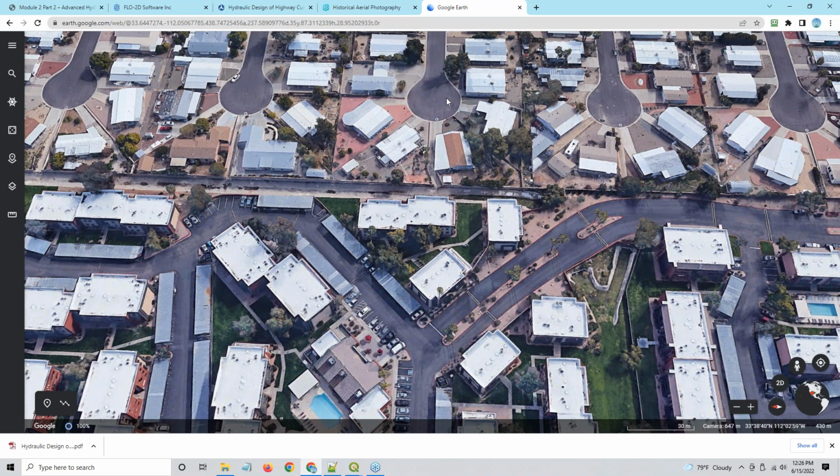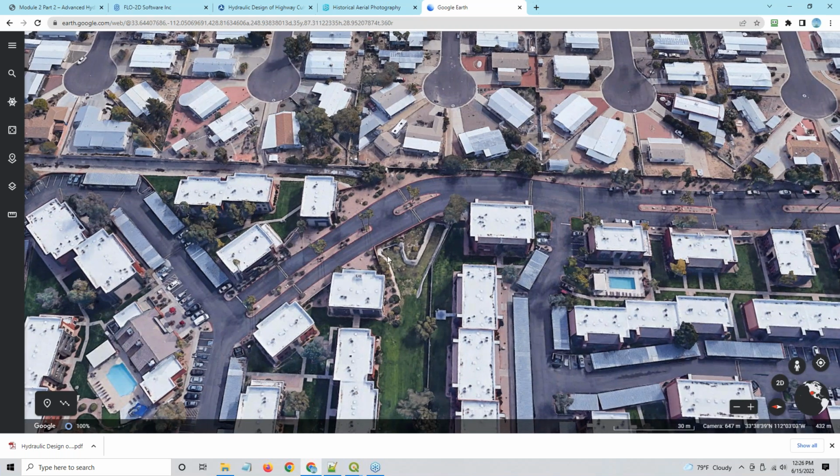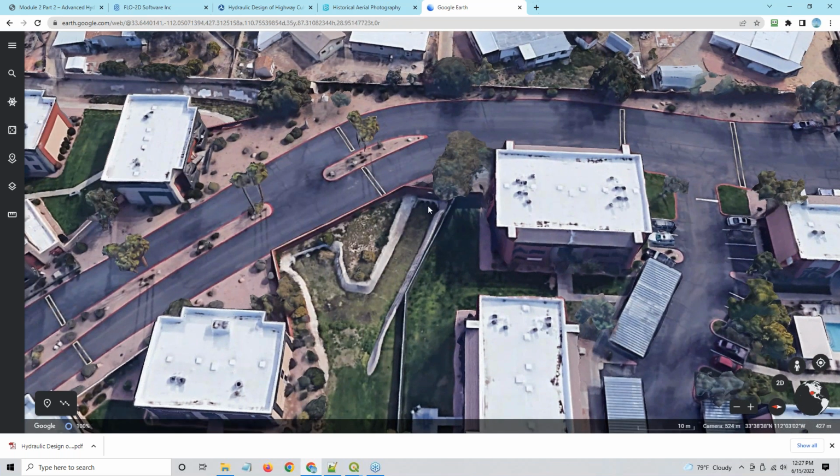So all of these cul-de-sacs drain to this drainage channel. It's just a little rectangular channel. And then they go through a hydraulic structure right here and into the outlet of the structure down here. Then there are some other ones that are connecting to this structure, but they're a little more complicated because there's no little drainage channel, because they put this road in instead. So these three are connected to this outlet through a pipe system. So you would probably set those up as storm drain, right?